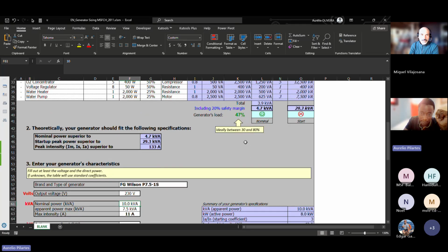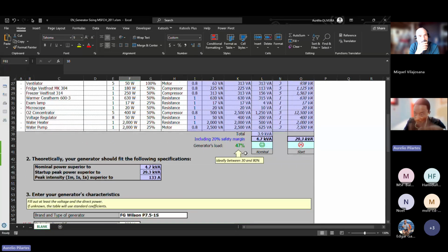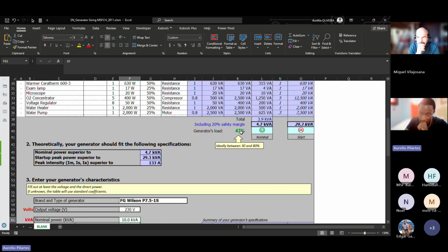And also because you have a variable load profile, there will be times, if you go with this power, when the load profile is low, where your generator will be running almost empty. And at those specific times, you'll be killing your generator. You will be shortening the lifespan of the generator. So this is why it's not even a good idea to start with in this approach.